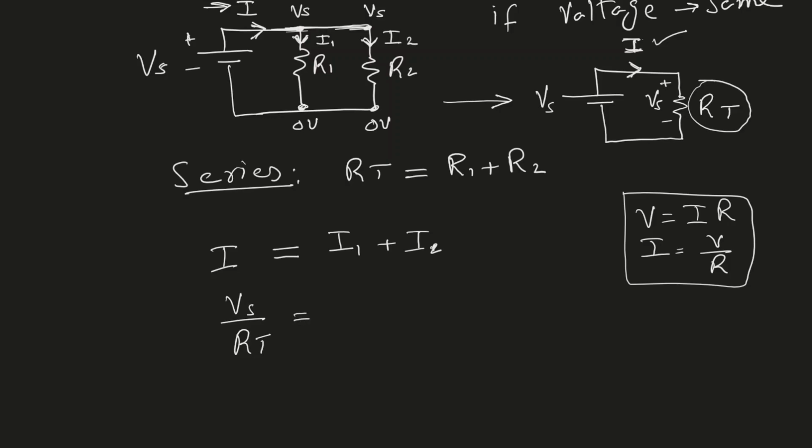All right, so we just applied Ohm's law. Now I want to apply the same Ohm's law to the resistor R1, in which the current I1 is flowing. And we know that the voltage drop across both of them is also Vs because they are connected in parallel. So I1 is the source voltage divided by R1, and I2 is equal to the source voltage divided by R2. So all we did is that we applied Ohm's law 3 times to each current.